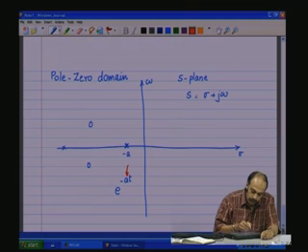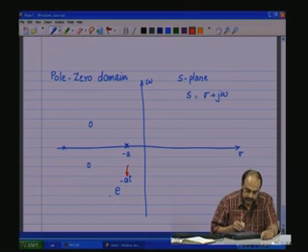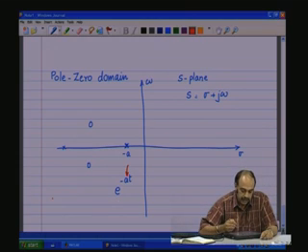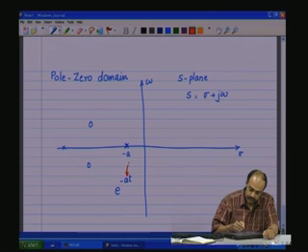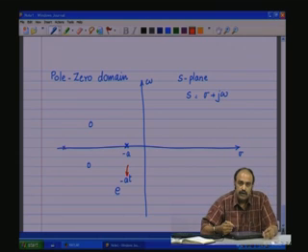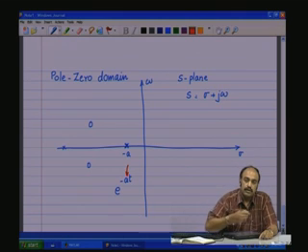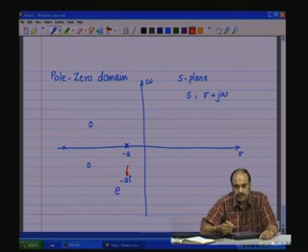So, each of the pole points here represents an exponential decay mechanism, such that any disturbance or an excitation will decay at a particular rate. Now, this gives a lot of insight about the system's dynamic behavior and the disturbance rejection behavior, which will not be obtained from the other two domains.